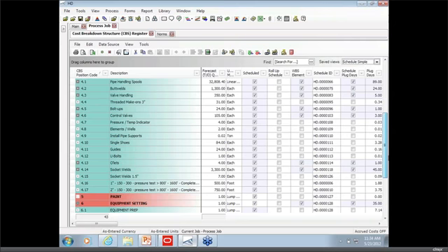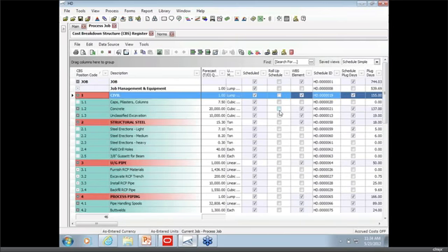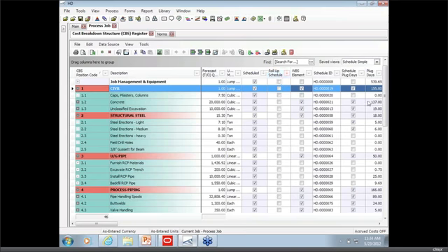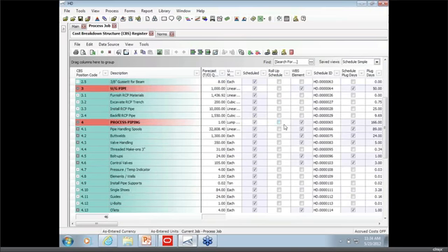the schedule here, in hard dollar, we're looking at essentially all my scheduled items. You can pick and choose how you want your data to be represented on the Primavera side. So right now I'm scheduling all the information, all the activities. If I wanted process piping to appear as one activity, I could just roll up everything below it instead of having those 17 items.